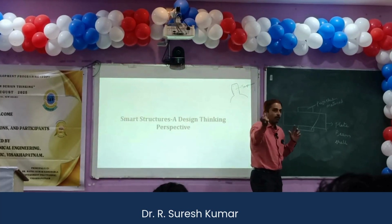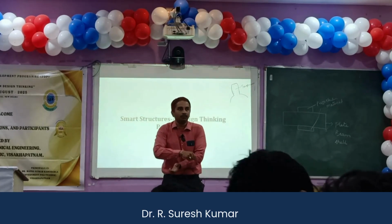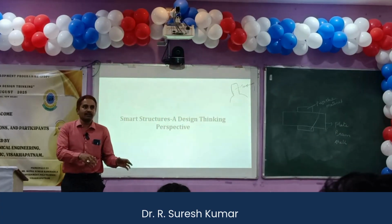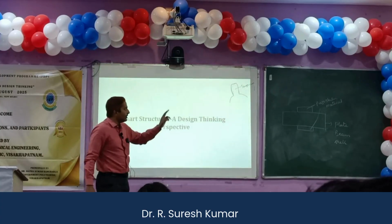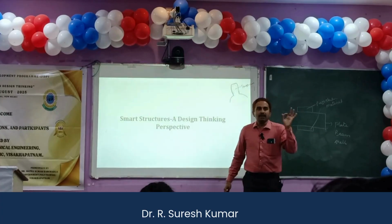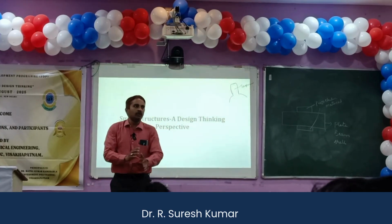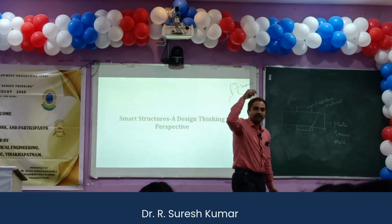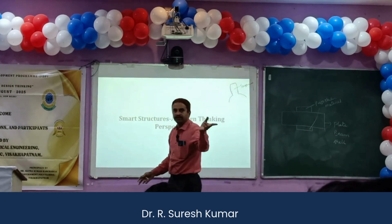Then Madame Curie observed that instead of applying stress, if you give voltage to the structure, what will happen? Once you give voltage to the structure, it will give mechanical output. So piezoelectric material has two effects, namely the direct effect and the converse effect. Direct effect is if you give mechanical input, you will get electrical output. But a converse effect is if you give electrical input, you will get mechanical output. So piezoelectric has both the effects.